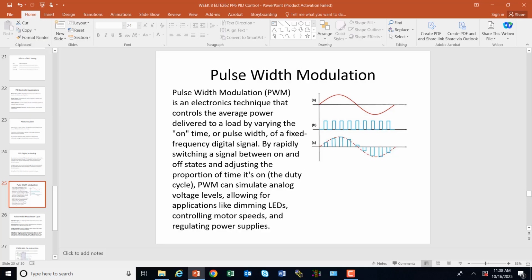What we're going to be doing with this is heating something with pulse width modulation. When it's cold, you are going to keep the heater on longer, and then pulse it off for a little bit, and then keep it on longer, and then pulse it off for a little bit. Then you might get into a medium heating range where it doesn't stay on as long, and when you get near the set temperature, it's not going to be on very much at all. It might just be pulsed to keep it at the temperature.